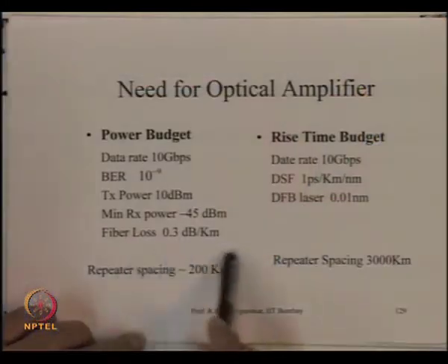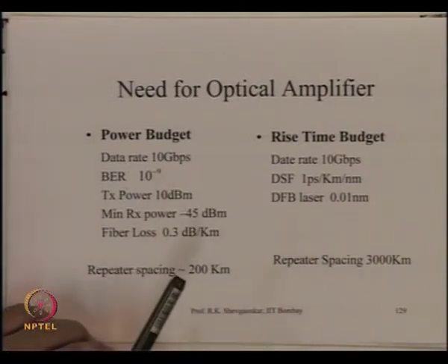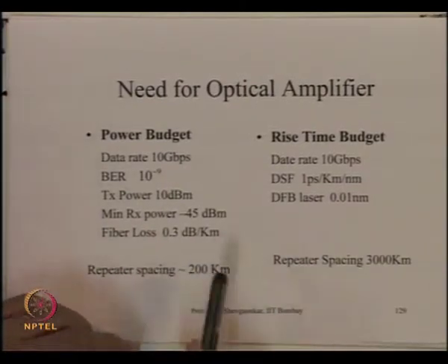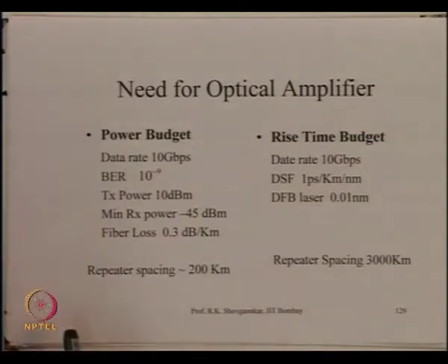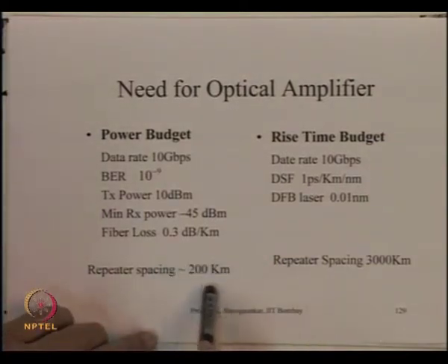So if the signal to noise ratio is the problem at a distance of about 200 kilometers, then there is no point in putting a whole regeneration system there. Just a simple amplifier at this location would do.